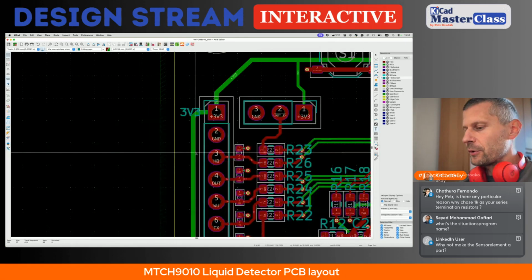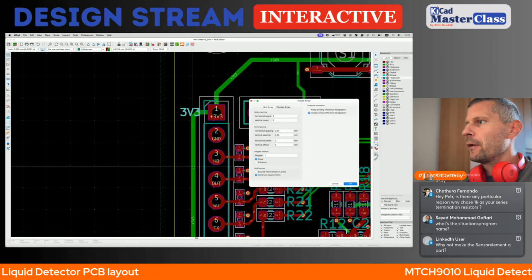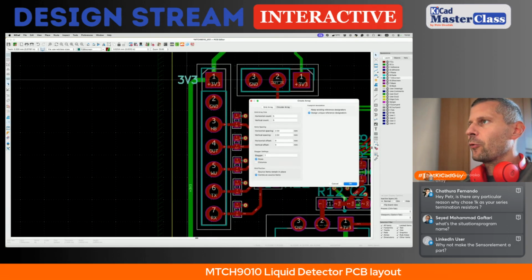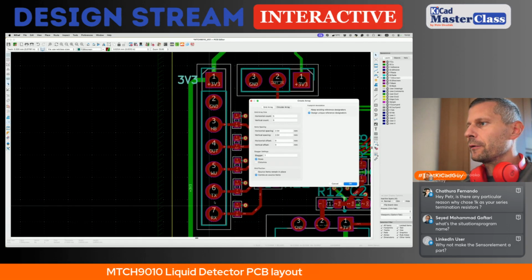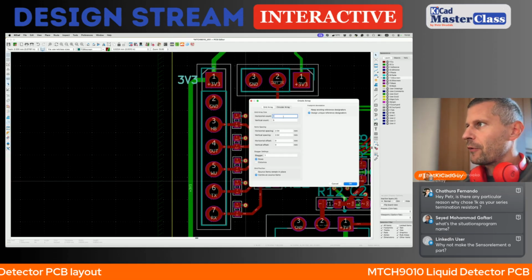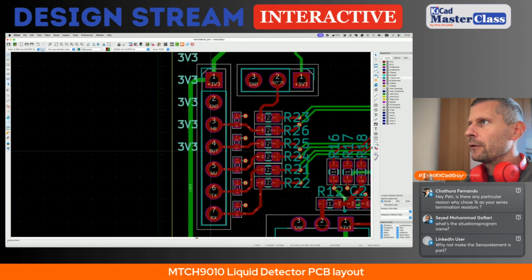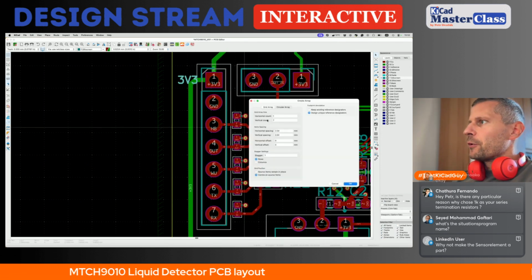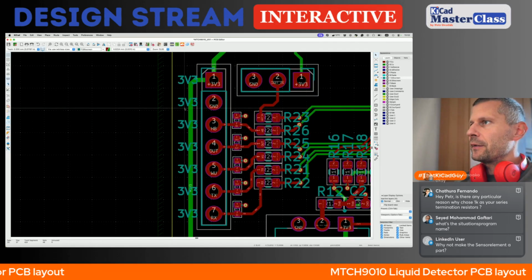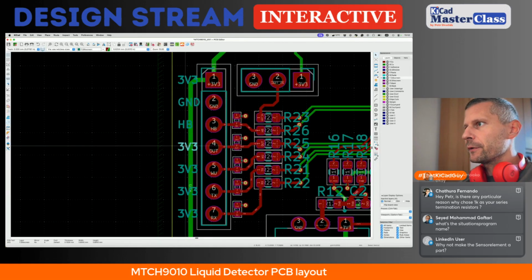And now I will use a trick: create array from the selection. We have a 7-pin header, and we want to copy this label next to each pad. So horizontal count will be 1, vertical will be 7, and spacing 2.54, but the source item remains in place like this. And now I only need to rename the labels.